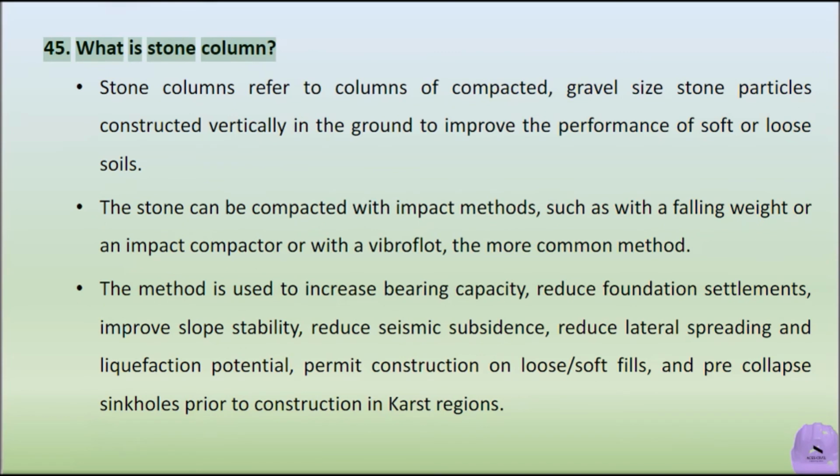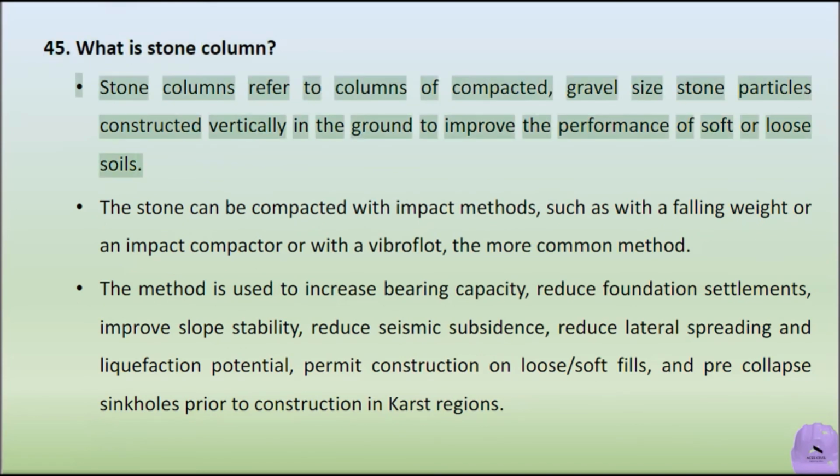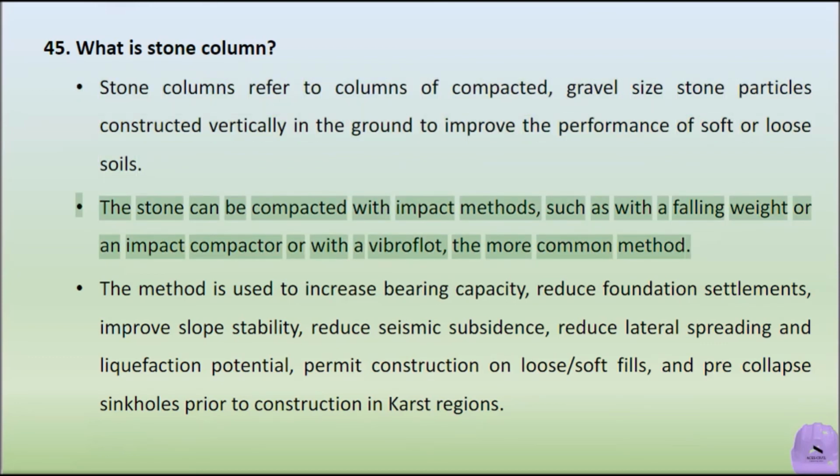What is stone column? Stone columns refer to columns of compacted, gravel-size stone particles constructed vertically in the ground to improve the performance of soft or loose soils. The stone can be compacted with impact methods, such as with a falling weight or an impact compactor, or with a vibrofloat, the more common method.